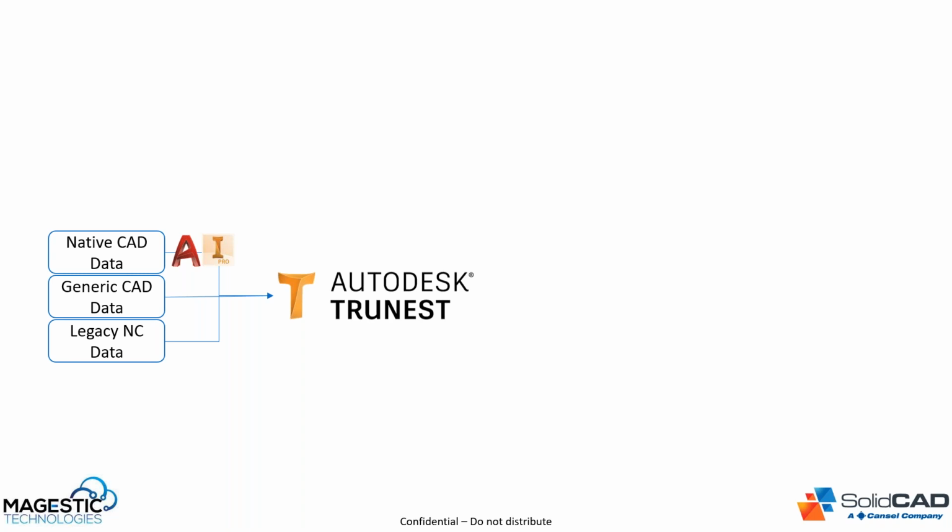If you have generic data like DXFs, IGES files, or DWG files, we can also support those in TruNest, as well as legacy NC data. So if you've got some cut files from the past that you want to transfer over, we can also bring those in and re-optimize those nests as well.